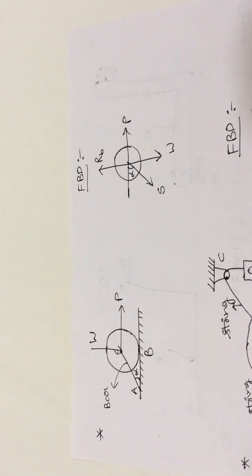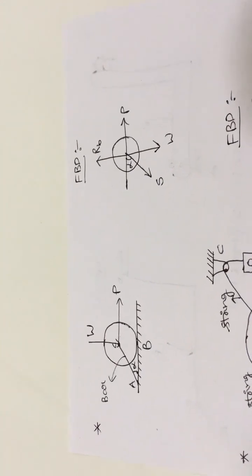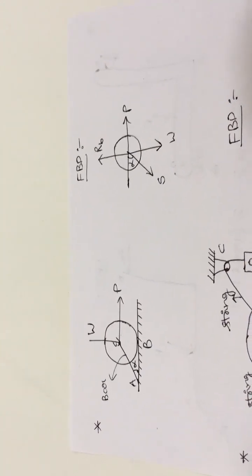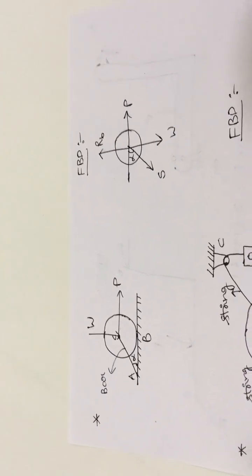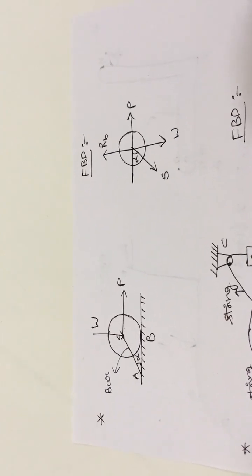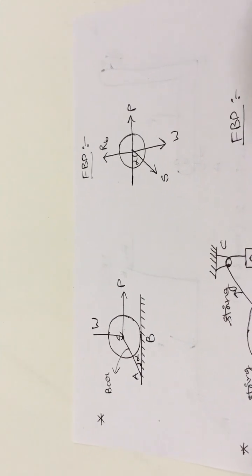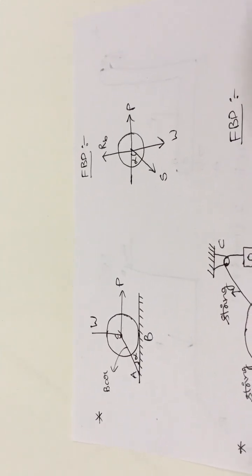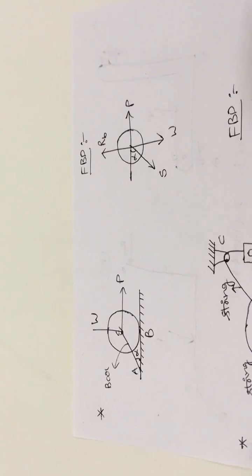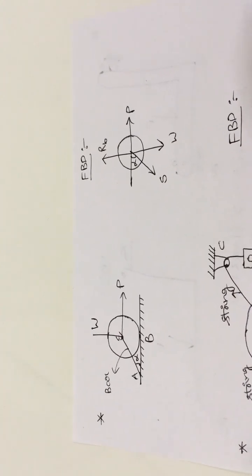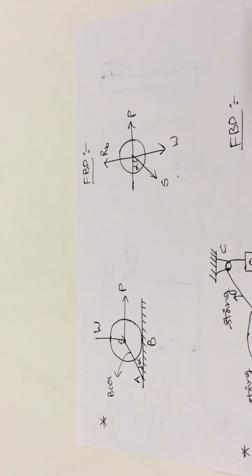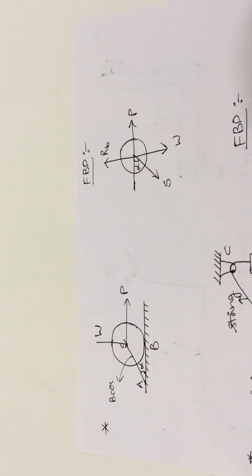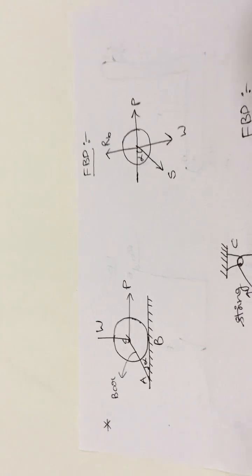So this is the procedure. First of all, for every problem there will be one free body diagram. For that free body diagram, you can draw the rectangular components force diagram. From that diagram, if you equate sigma H and sigma V equal to 0 or sigma M equal to 0 according to the given data, we will get the equations. By solving those equations, you can calculate the reaction forces for that particular body. Now we will see some examples.